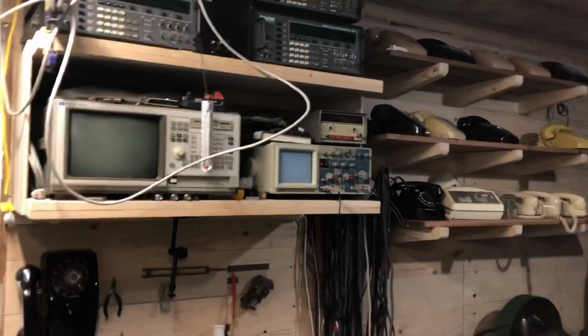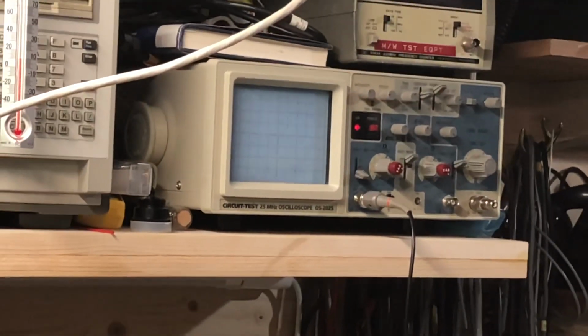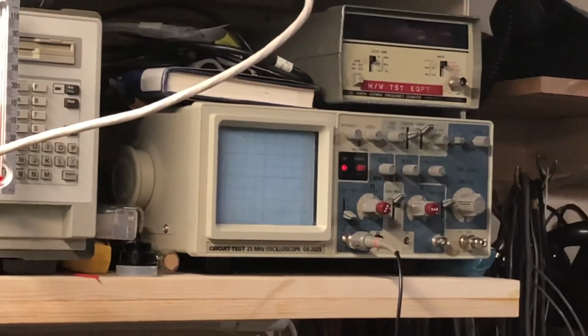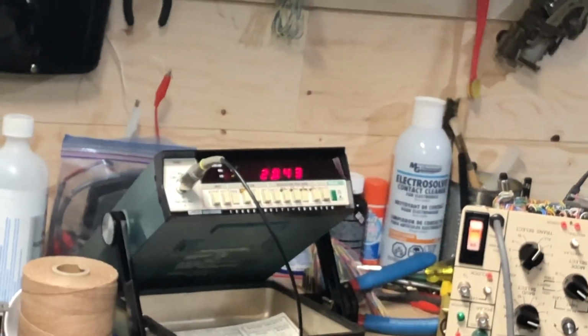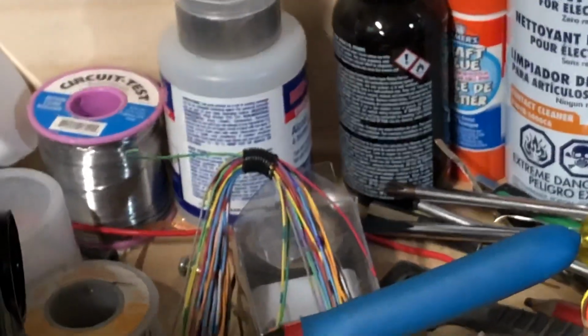So when you watch the scope, zoom in, I push a key, you can see something comes alive, but that's it. Otherwise that card is idle, there's no signal. If you look at the frequency counter, I couldn't get a clean count out of it because even with a continuous signal, the gaps between the characters were causing gaps in the signal up here.